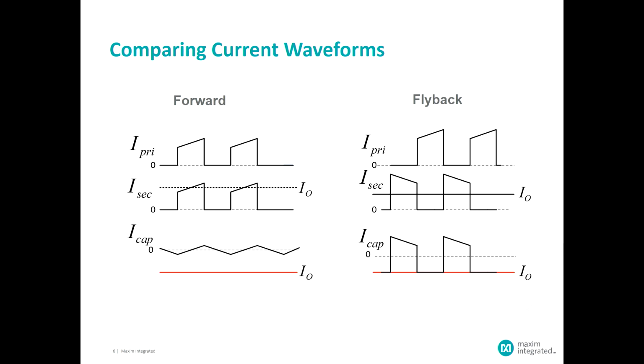And what we're seeing in the capacitor waveform is the output capacitor now, which gets recharged when the primary and secondary currents are flowing, and which gets discharged when the current is only in the output inductor, which is not shown there, but that occurs when the transformer is not conducting any current in either winding. So the current in the capacitor is just a small AC ripple current caused by the value of the output inductor, which we talked about in earlier modules.